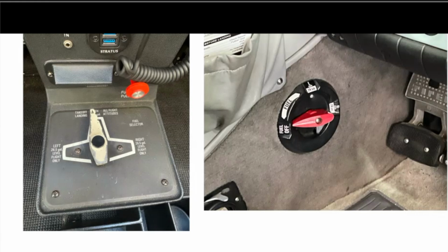When that's in, it's on, you're good, but you're always on left tank, right tank, or both tanks. Okay, this is a 172. Where's our tanks here? Up high, so there's a gravity fed system, right? In flight, you're going to be set to both. You're going to let gravity do its deal, and you're not going to pick one tank. The system's going to take fuel from both sides, and you're going to maintain that weight balance within the aircraft by just setting it to both. Typically, you're going to set it to left or right when you're on the ground, okay?